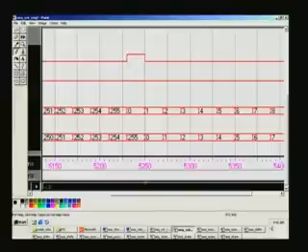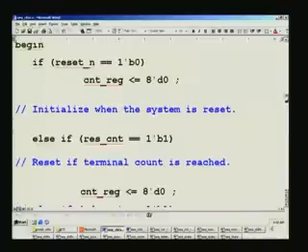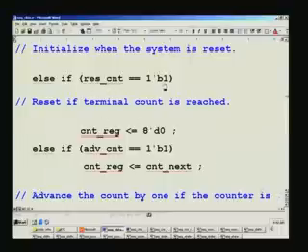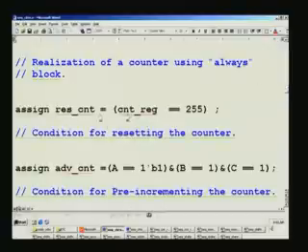So, you can see this signal here, which resets the counter. This is the same as this 255, same duration, because it is a combinational circuit. So, when reset count has become 1, that is, reset count is 1 if counter edge is equal to 255, then only this action takes place, and this is a combinational circuit as we have seen. So the moment 255 is encountered, immediately it will go without delay. Of course, there will be a gate delay, only after back annotation we can see.